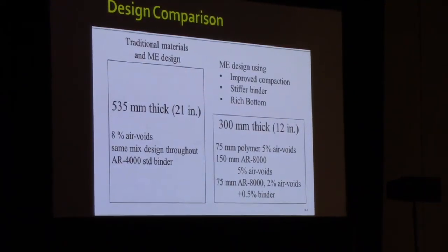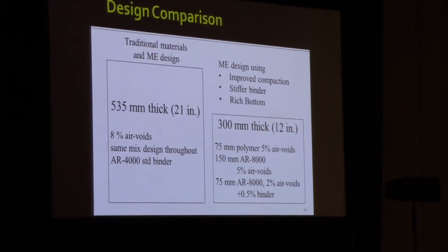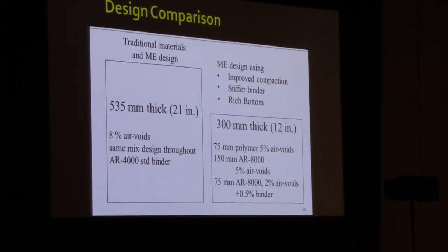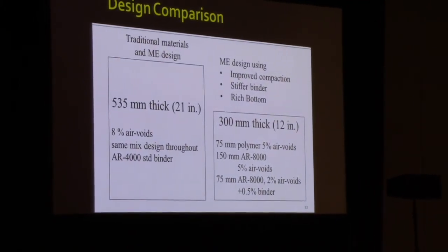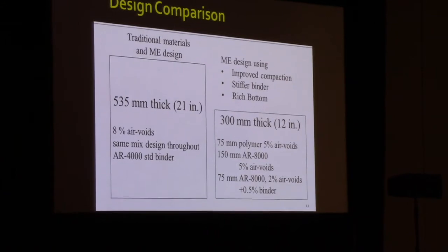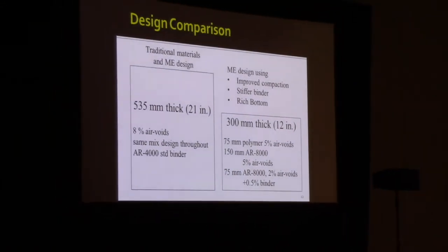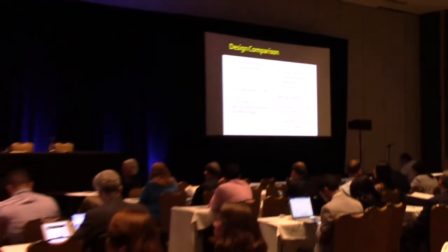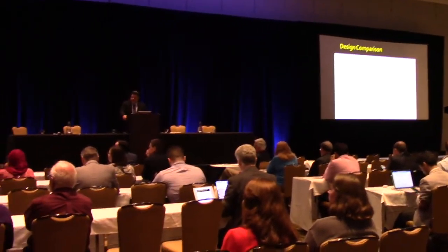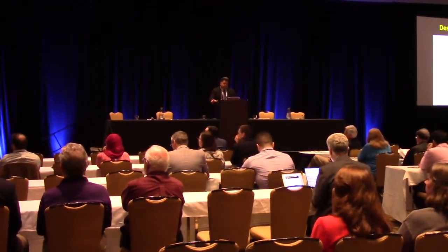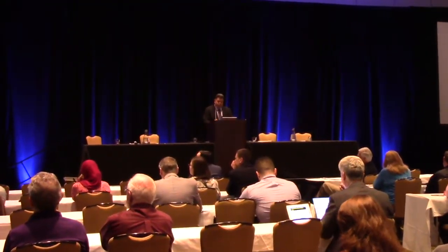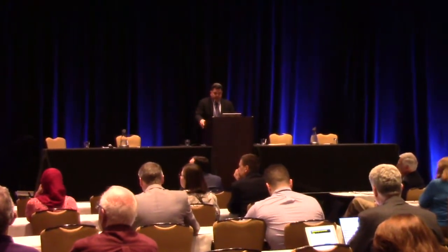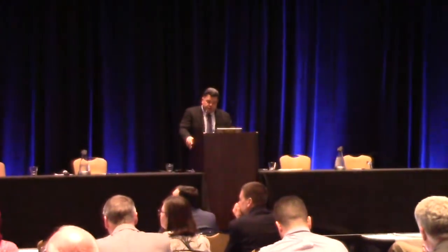So at this point, we start to look at what's that design. Let's start with the design and thinning it up. For most of you, all of you in here, are very familiar with moving towards a long-life, perpetual pavement design, and that's really what was employed here. So taking advantage of the latest in understanding of design and in materials, and being able to reduce our sections, become more efficient there. You're looking at about a 30-year design based off of 250 million ESALs.